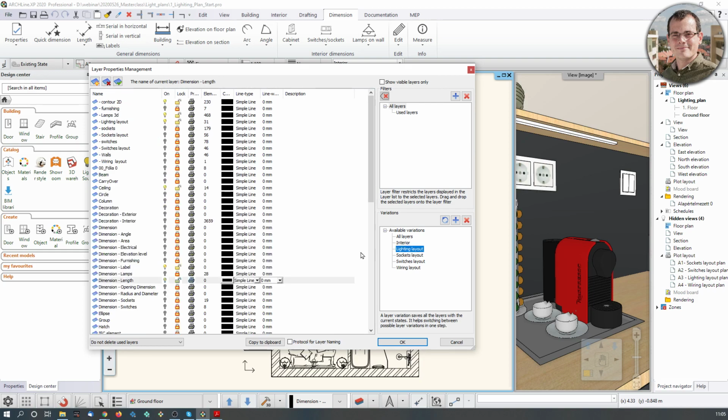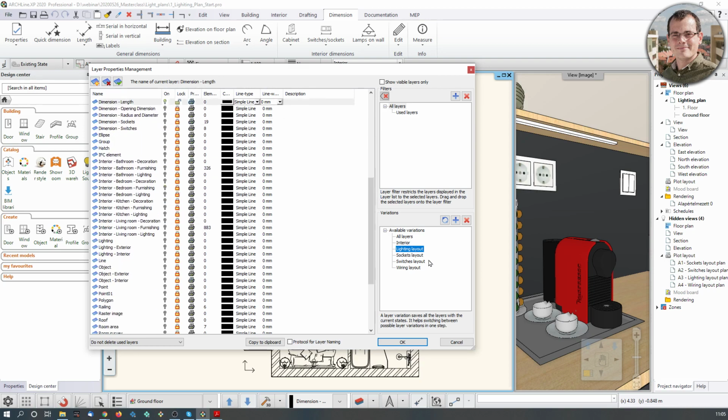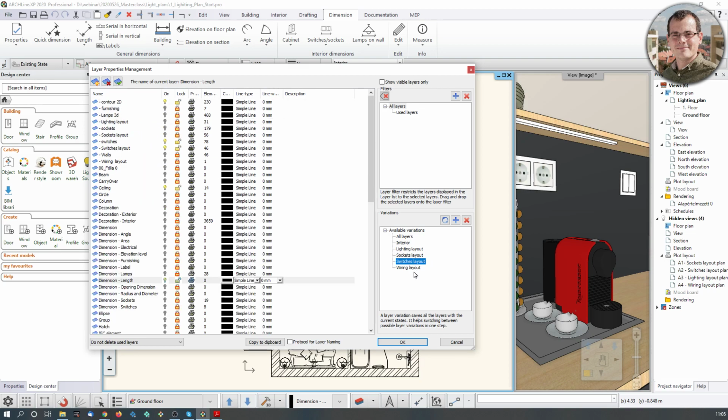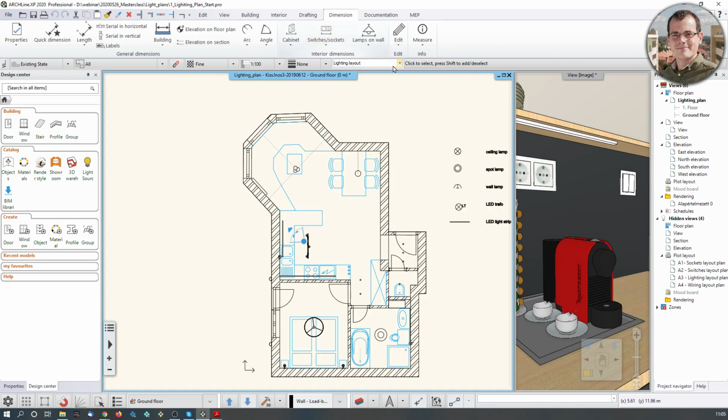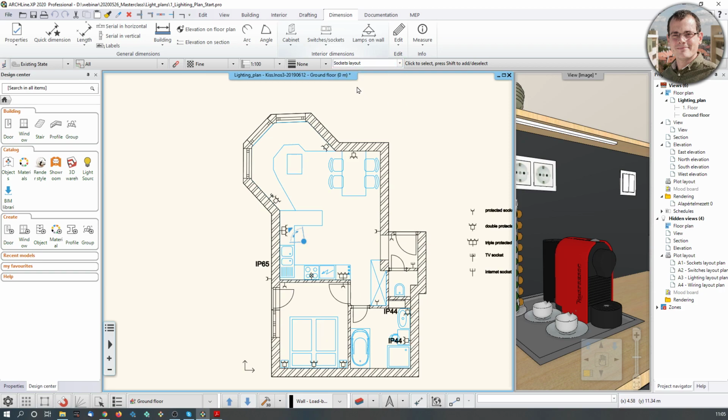Similarly, for the lighting layout, we have almost everything turned off except for the important parts about lighting elements and fixtures. And so on, we have another few layouts here. Now, the reason why we have this is because when we go up here into this view control bar, you can filter what you want to show and what you want to hide. So if you carefully collect the elements into these kinds of groups, then you can easily filter down to the things that you actually need.